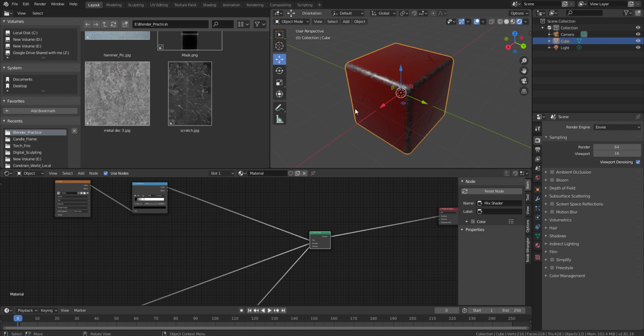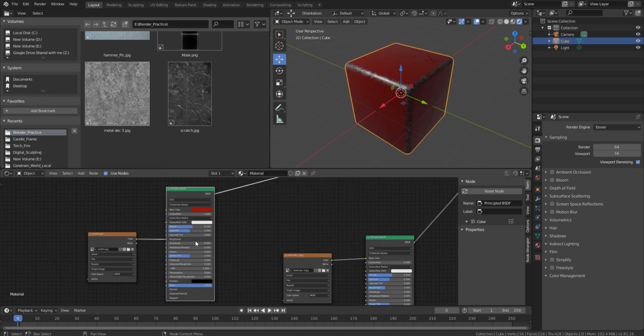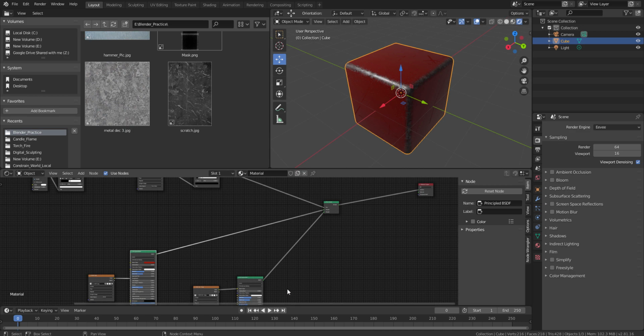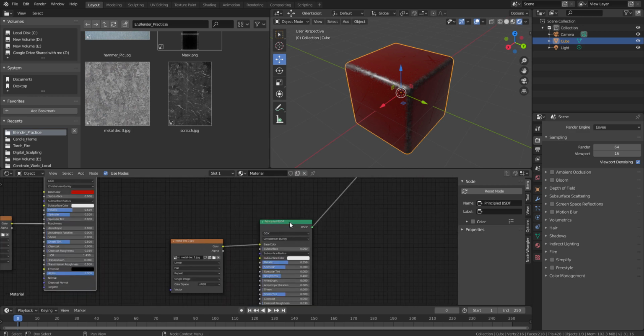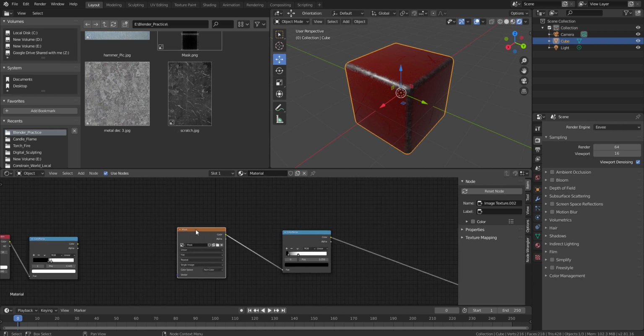So there are two layers. I'm just summing up the entire thing. The first layer, the top layer, is the painted one, which has certain scratches which I've used, with an image connected to the roughness. Another one is the base one, which is again a Principled BSDF with a metallic image, and the third one is a mask one, which I'm going to explain, because that is the one which gives you control over your edge wearing effect.